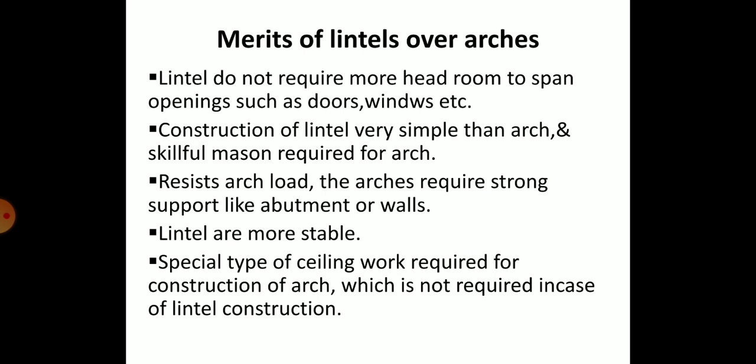Then, to resist the arch load, arches require strong support like an abutment or wall, which is not required in the case of a lintel. Also, lintels are more stable. A special type of centering work is required for the construction of arches, which is not required in the case of lintel construction. For arches centering work is necessary, but it is not required for lintel construction.